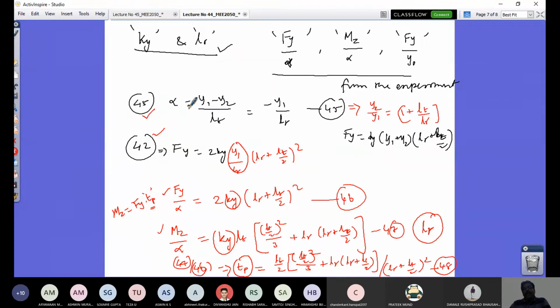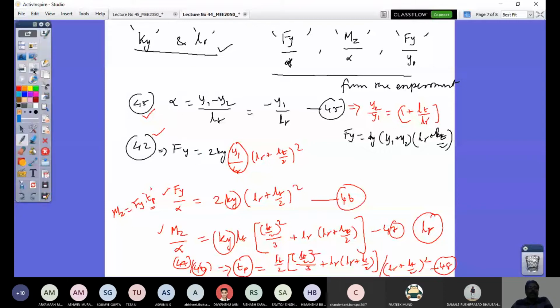That is another difference from Julian's model for longitudinal dynamics, wherein Fx, or braking effort, is explicitly a function of slip. Here the string model gives you the expression, but it does not explicitly show Fy as a function of alpha, the slip angle. So that is another difference. The first difference is that they are independent models: one does not consider slip angle, the other does not consider longitudinal slip or skid.